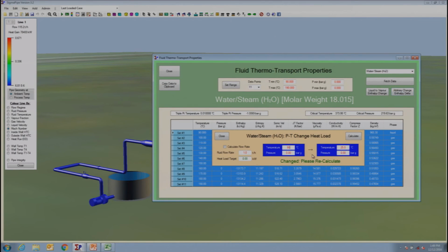We're going from 90 degrees to 170 before the acceleration into that pipe, and we're telling it that it's using 78,400 kilowatts. It calculates 116 tons an hour, which is very close to that number. Of course, this is a simple thermodynamic calculation without taking any kinetic energy effects into account, but it's approximately correct. So it's inherently telling you the right story.